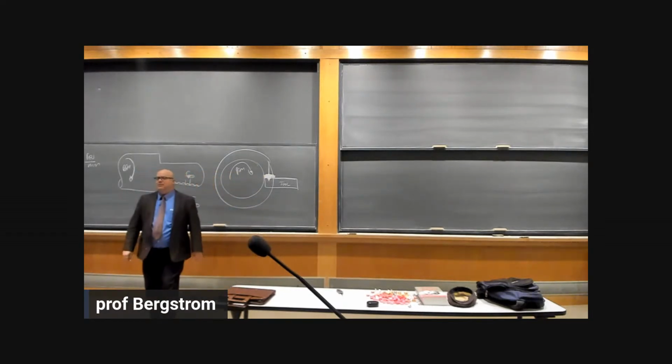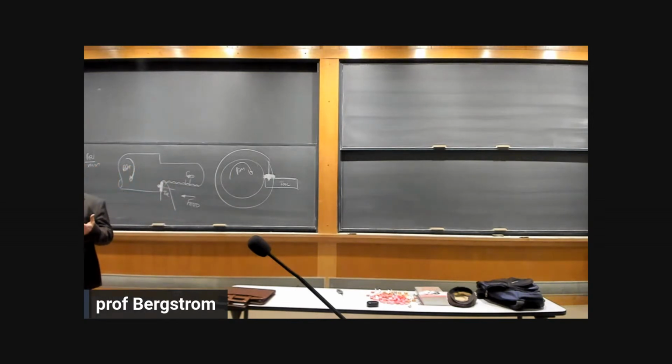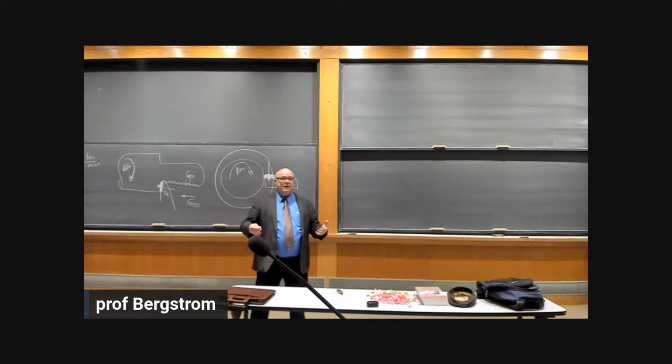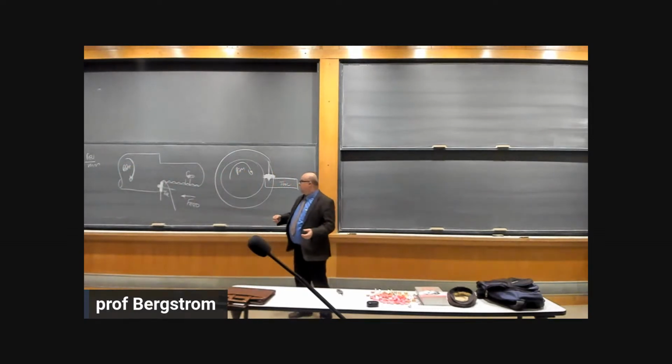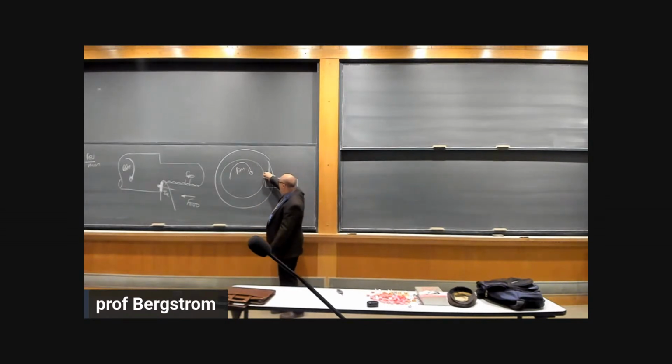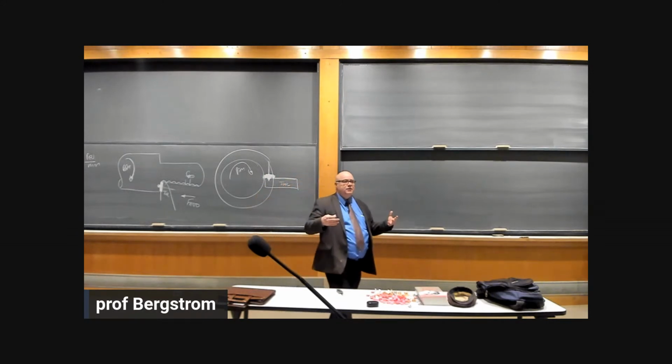So for this diameter, here's the minimum, here's the maximum, use the average. What I usually use when I'm doing a calculation like this is the one that would be worst if it was bad. So if I'm worried about too fast, I use the big one. If I'm worried about too small, I use the little one. But in general, you can use the average of those two.